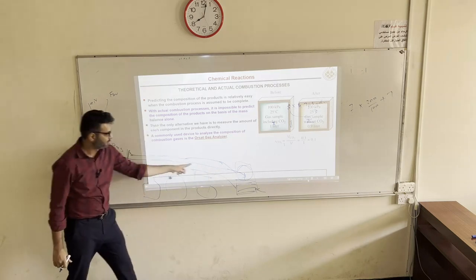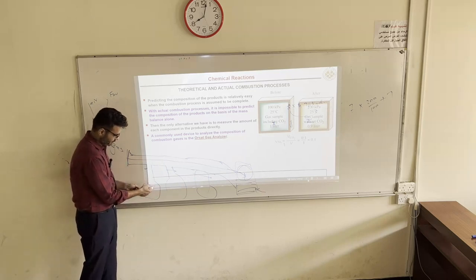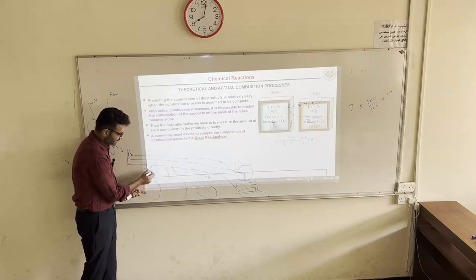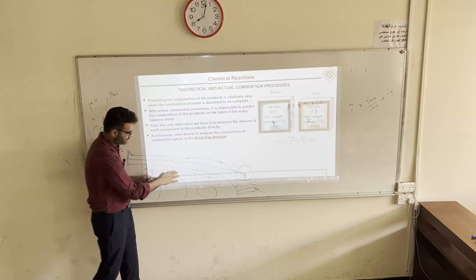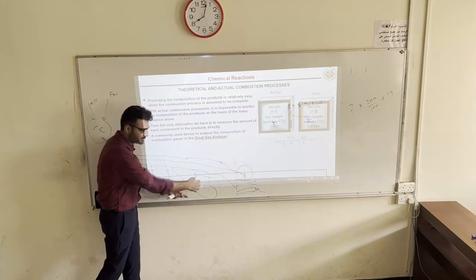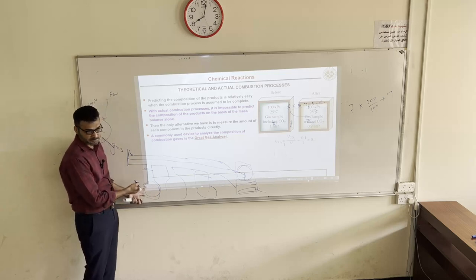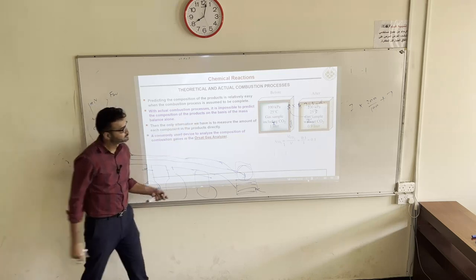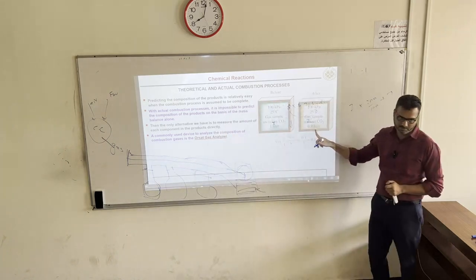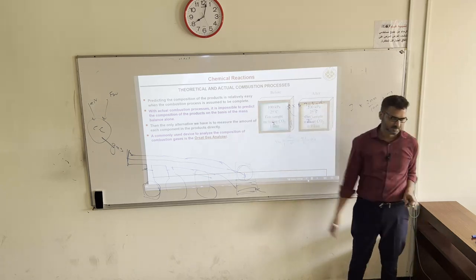So this gas will flow here, it will stay here for a certain time. Whatever CO2 is present will be absorbed by that fluid, and then you will close it. Then you will open this one so that the remaining, whatever is there, H2O, will be absorbed here, and so on. And you will measure the volume before and after. Now CO2 is removed, now the volume has dropped. So it means 0.1 liter was CO2 which was absorbed. So this is such an experimental technique.